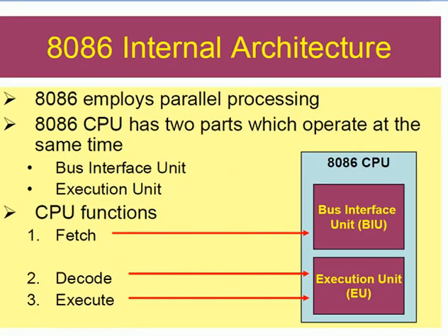Basically, the architecture is divided into two types. First one is the bus interface unit, second one is the execution unit. You know very well the bus interface unit. How to execute an instruction: first fetch the instruction, decode the instruction, execute the instruction, and store the result. Read the instruction from the memory, then decode that instruction, and then execute it in the arithmetic and logical unit, and then it can store the result again in the accumulator register.